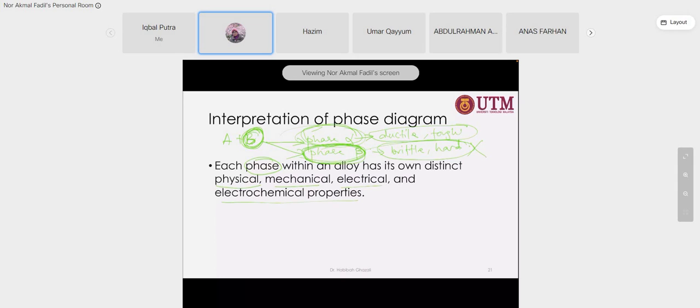Okay, because alpha and beta will have different properties, you have to know, if you want to make or choose an alloy, what kind of phases you will get. Okay, you cannot just simply say, oh, if I add carbon into this iron, it means my iron will become strong. No, not like that. You have to ensure how many percent of carbon need to be added in your alloy, so that it will produce the desired properties for your design.